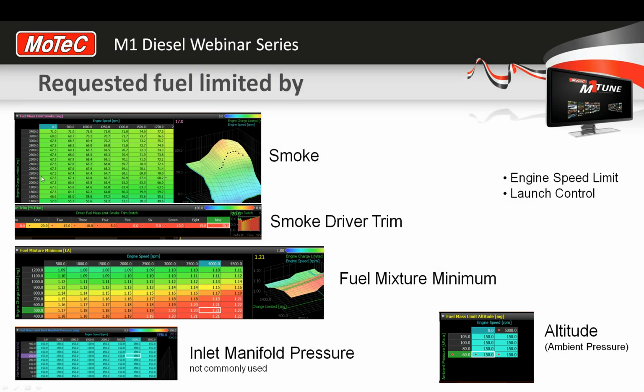Alright, so here's our smoke table, and we have engine charge limited, engine charge unlimited. This is basically our airflow meter on the vertical axis, or if that's not working, our engine efficiency table, calculating the amount of air going into the cylinder. And remember, in a previous webinar we explained what that was represented as, and that is in milligrams or weight of air.